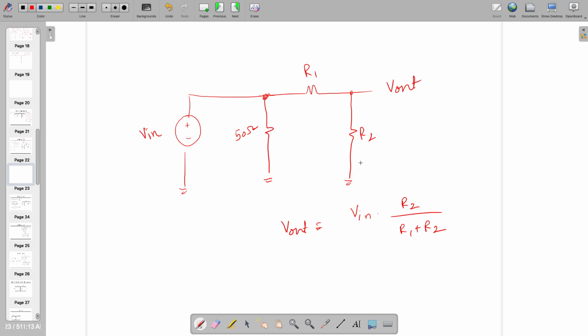Look, you have to follow one thing. This is an independent voltage source. If this is V in, any impedance you are connecting here for an independent voltage source, it cannot change. It will change if you are adding some resistance here, then it will change. But if nothing is there, there is no voltage drop, so it will be V in only. Across this point and this point, you can apply anything, it has to be V in.